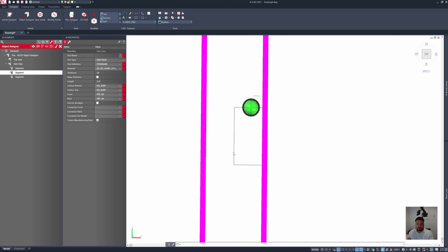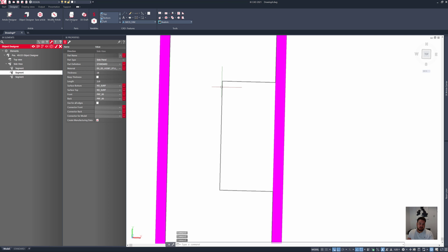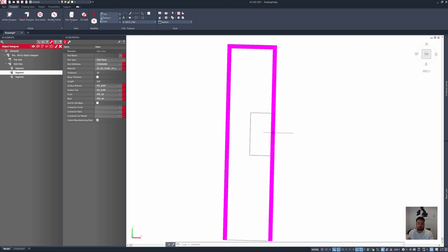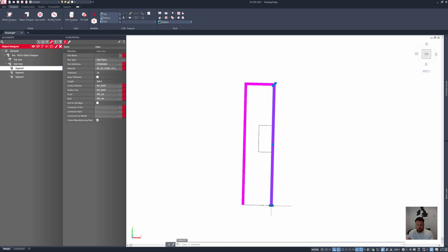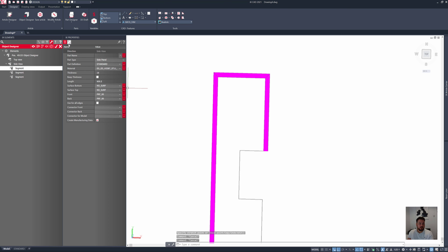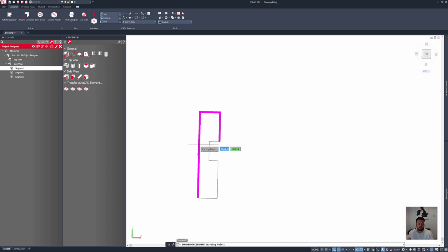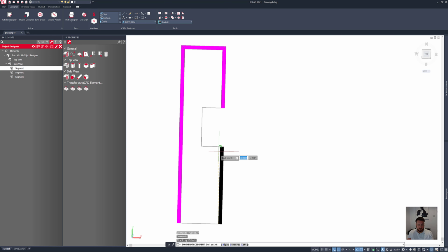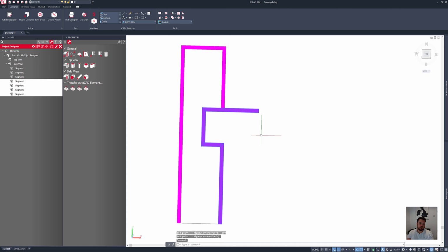Now in here, to actually physically make these things, we want to have these nice and clean as a square corner in here in case we need to put some material in here. So if I just come up, for example, I can drag this all the way up here and then add in some other sections in here if need be. So if I come in, for example, and do another side view segment, I might want to come up, miter into here, run around, and then come out this way 300 millimeters, like this for example.